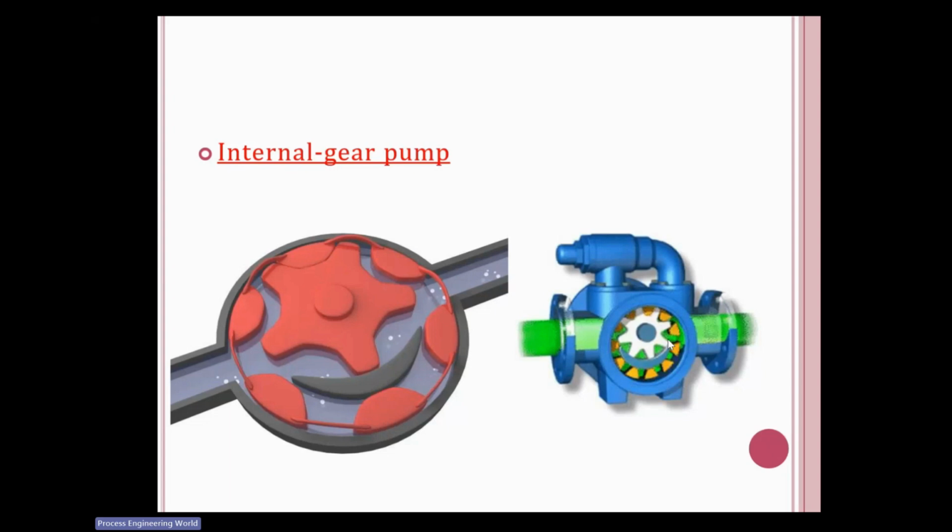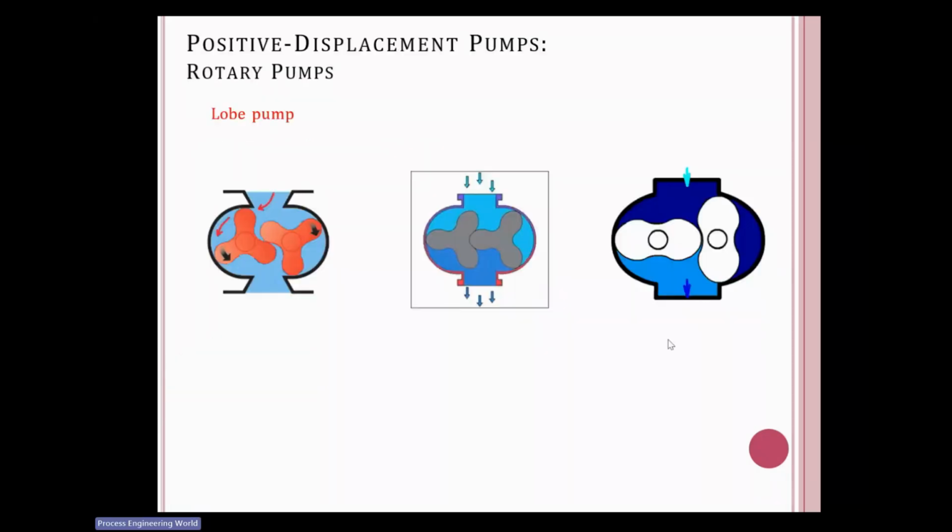Okay. So is it clear till here, everyone? Yes, sir. Okay. So we have one more category in positive displacement pumps, the lobe pump. It also operates on the same criteria. Instead of plungers or gears, what you have here are wooden lobes or metallic lobes or metallic-lined lobes.